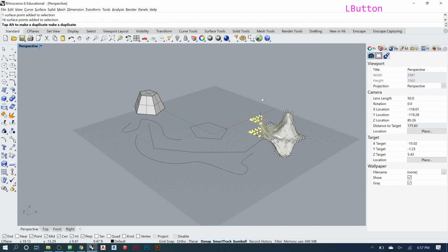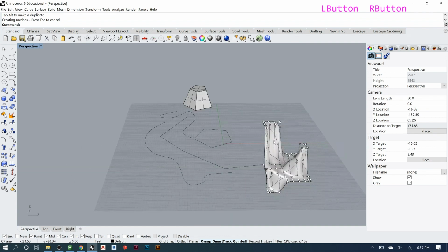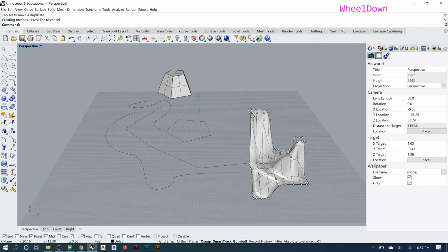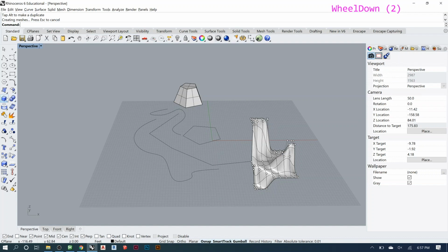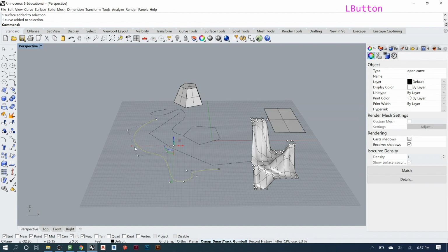And the more you have, so see here how this looks like a piece of cheese that's melted all over. If you have fewer control points, you actually get less control, and that results in a smoother curve. The more control points you have, the tighter your curves can be. Notice here I only have 3, and that curve is nice and long and smooth, whereas here I have 5, and the curve can be really tight and twisty.